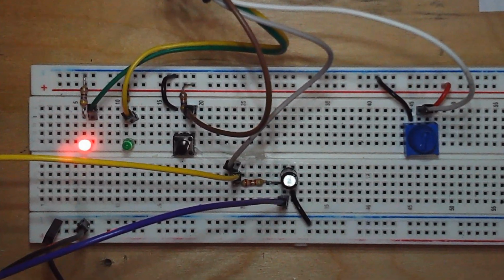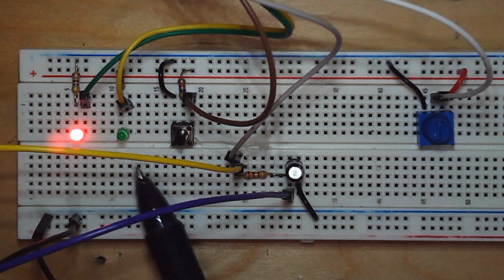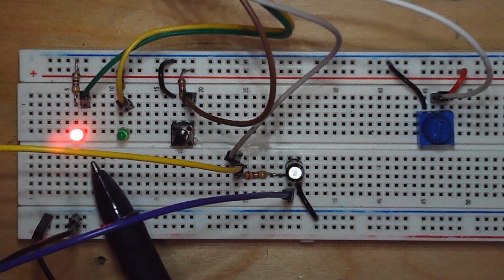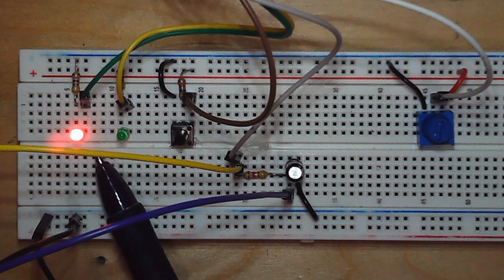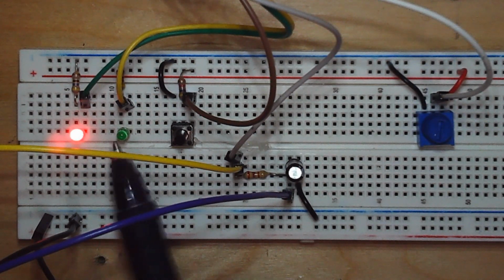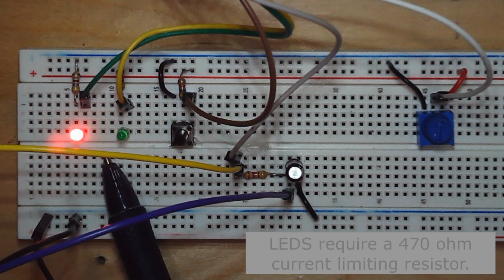Hello, this is the Lab 1 hardware, and I want to point out a few different items on the circuit. First of all, we have a couple of LEDs, and I believe they're connected to pins 8 and 9. The red LED has two leads. The anode lead is the longer one, and it has to be in series with a 470 ohm current limiting resistor. This gives you about 7 milliamps.